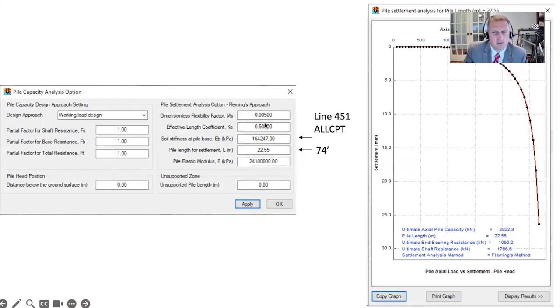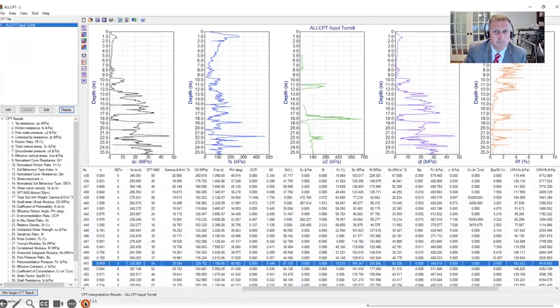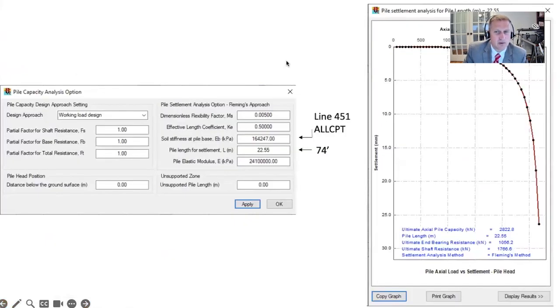In addition to doing that, I can also develop a top-down load displacement curve. I need that load displacement curve to both find the geotechnical capacity and also to find out how much toe movement is going to happen from this pile. Because we're going to compare both the toe movement and the end-bearing capacity, I need to know that. So let's go back real quick.